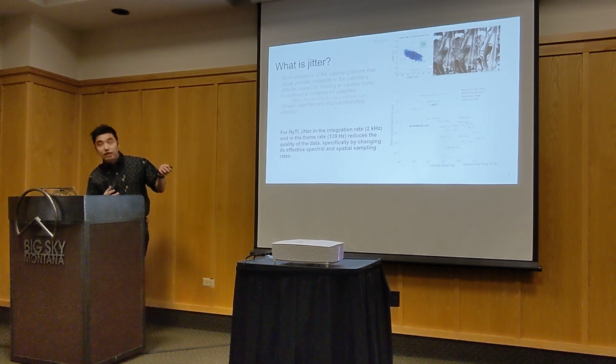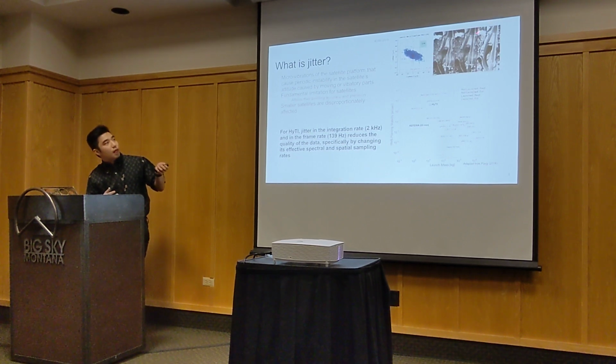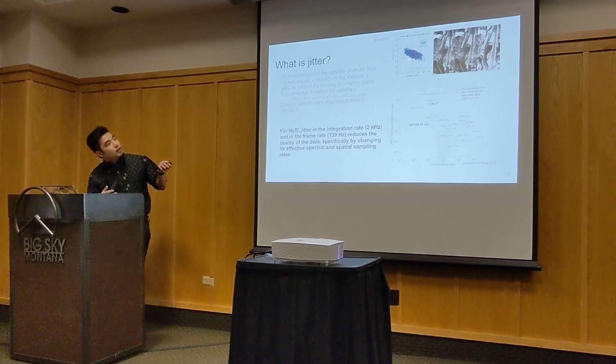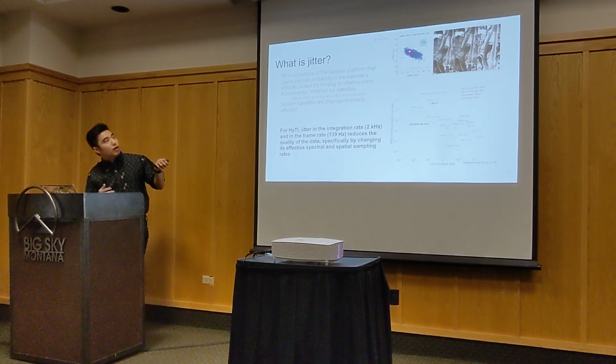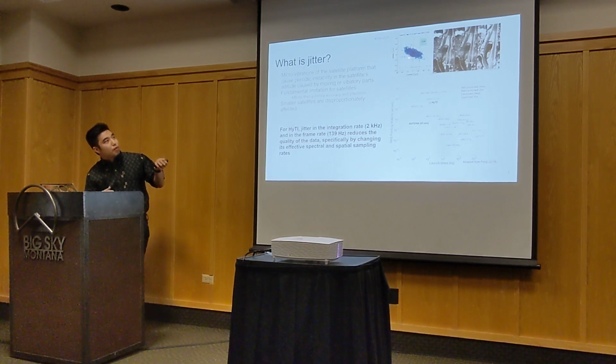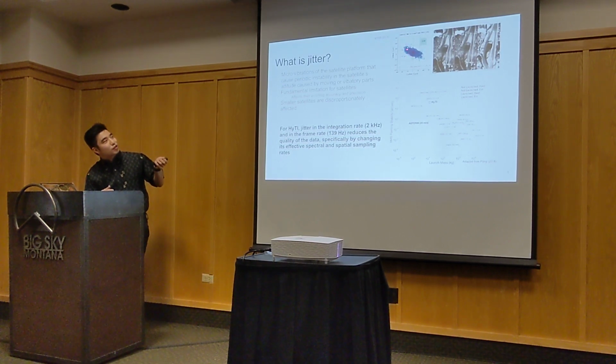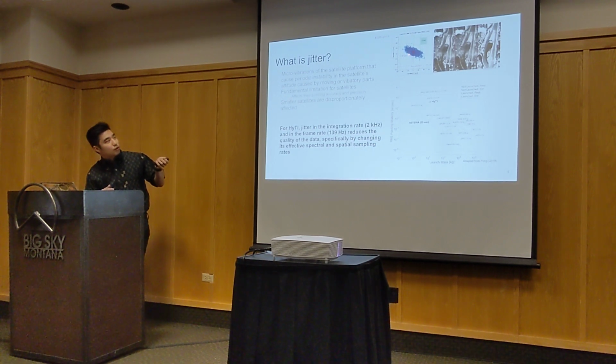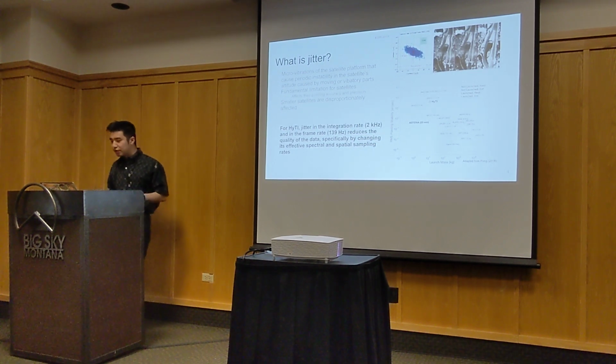This left here is an image that is uncorrected for jitter, it's blurred. And as you move right, the jitter correction kicks in, and it's nice and sharp. This image here is a centroid map on the focal plane, and you can see this random semi-periodic structure in the jitter against the circled requirement there. And jitter is a fundamental limitation for all satellites as it affects their pointing precision and accuracy.